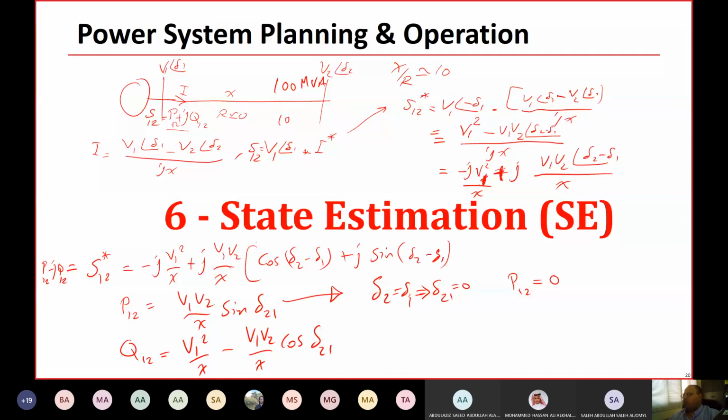If the line loading is very low, this will enhance the security of the system. And if we have any disconnection, you still have 90 megawatt to be injected in this transmission line without any problem. And if you have the transmission line at 100 mega, at full capacity, and you have a disconnection anywhere, one transmission line is out, so the power flow will increase here, and your system in this case will not be secure. Am I right?